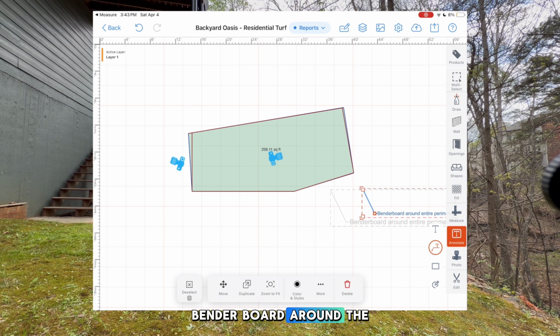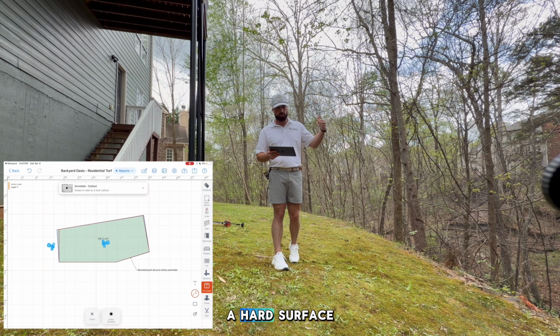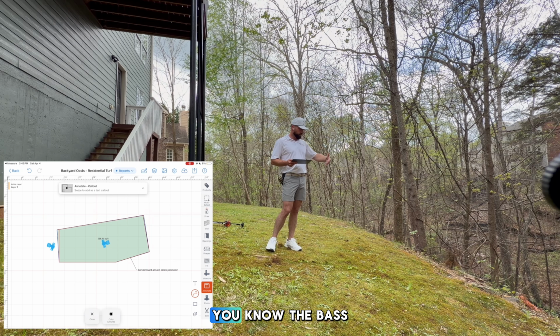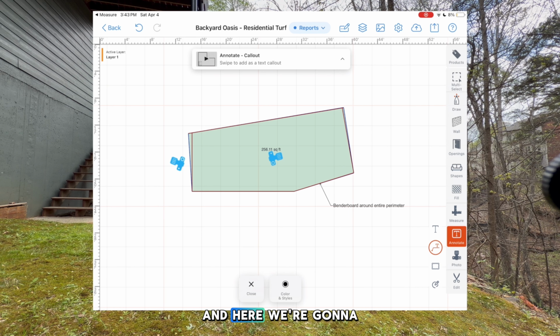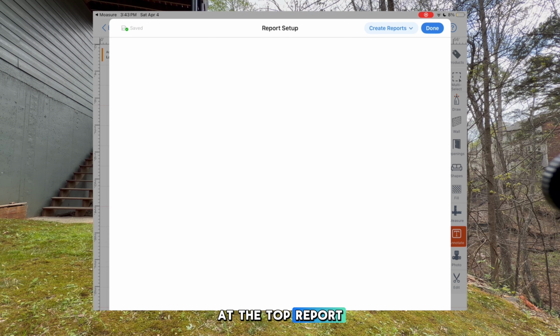Bender board around the entire perimeter is not necessary, only if there's not a hard surface the turf is meeting up to. In this instance, there's not. You want to keep the turf essentially from, the base coming out because there is a bit of a slope here. So we're going to keep that. We got that note. That looks good. So boom.